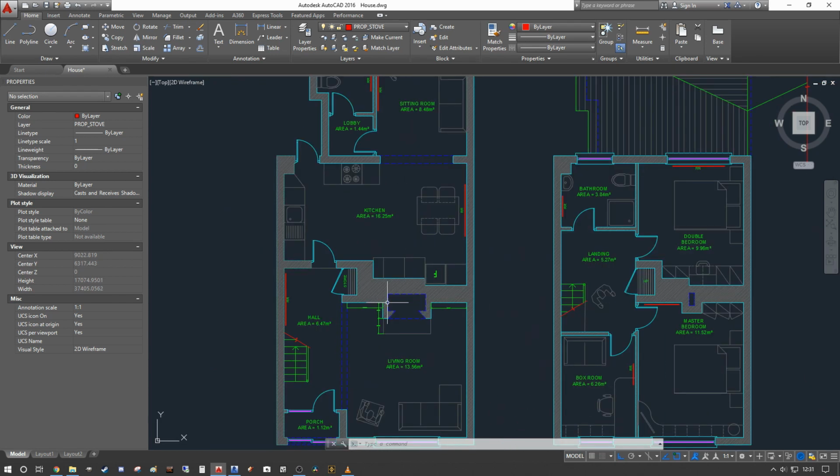The reason why this is important is we want the visibility of all our lines to be assigned by the correct layer before we take it into Revit, so that gives us the visibility control of the CAD file within the Revit environment. If all the CAD objects are not assigned correctly to color by layer, then you will not have the ability to manipulate the presentation of those lines in the Revit environment either.